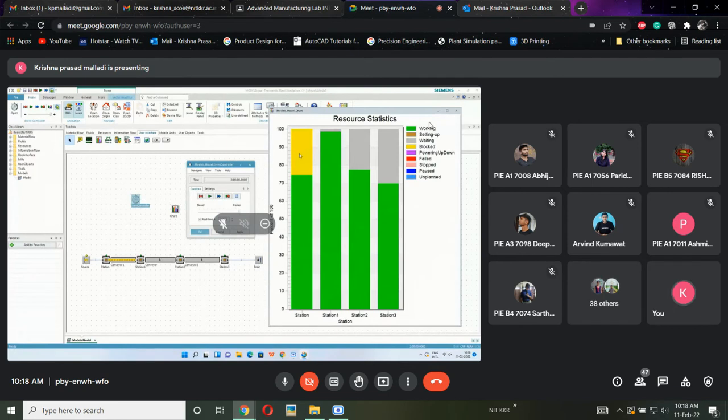Okay. So blockage is nothing but work in progress inventory. See, there are a lot of parts that are waiting for this machine, which is in no way acceptable for industry. Either the machine can wait for a part, that is acceptable, that can be managed. Now these two machines have a waiting phase. I can increase by different means, whereas this blockage, I will try to reduce. There is a possibility to reduce this one.